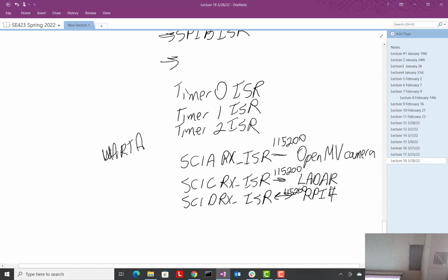So what this receive interrupt does, it occurs when there is one character received from the device it's connected to. So how often is that happening? If we're sending data across, and remember, when the LiDAR is giving us data, I think it's something like 447 bytes that need to come across. And when it starts sending those, it just keeps on sending, one right after the other, until all 447 have been received by us, by the red board. Okay? So let's think about that.